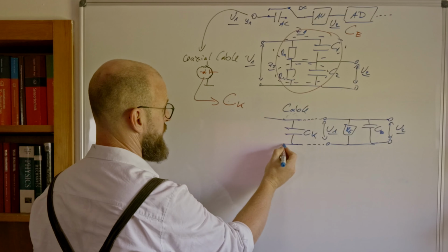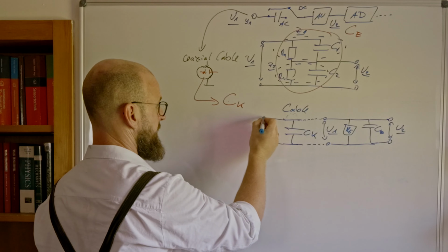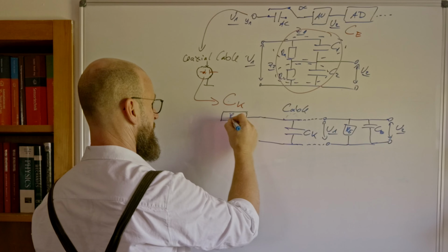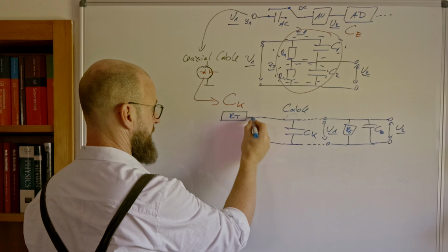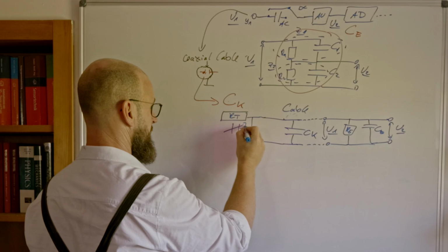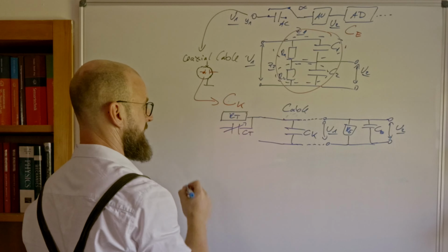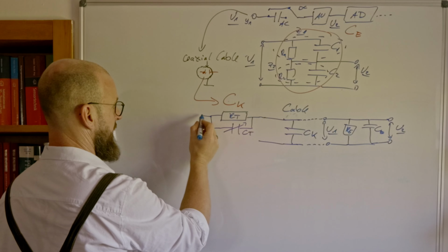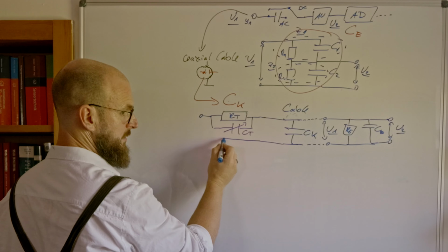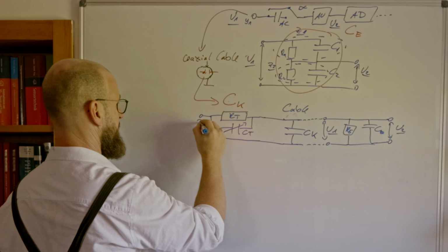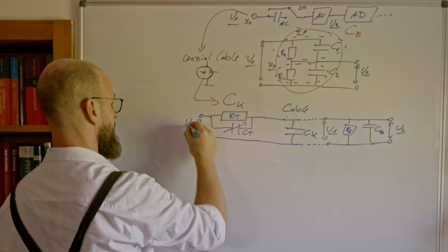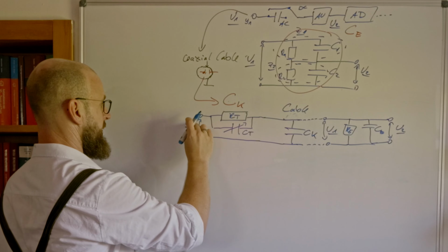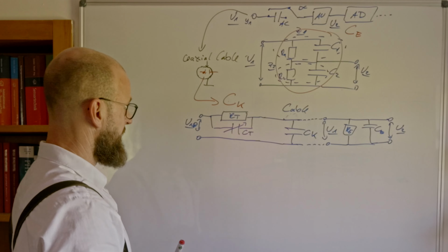We use a probe. Again, we use a special unit which holds its own resistance RT and adjustable capacitance CT like that, and which now is connected to your desirable signal U1, let's call it E or P, so it's clear it's the signal we record by the probe.